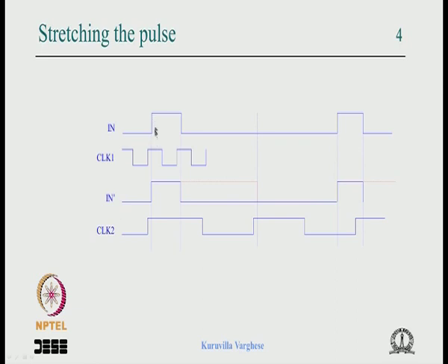For this change to be detected in a very straightforward way, one would expect a clock period matching this pulse width. But we know that the frequency is quite low. So definitely this pulse width is not the criterion for choosing the minimum clock frequency of the state machine or the controller.